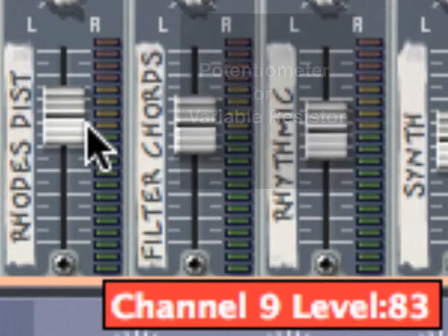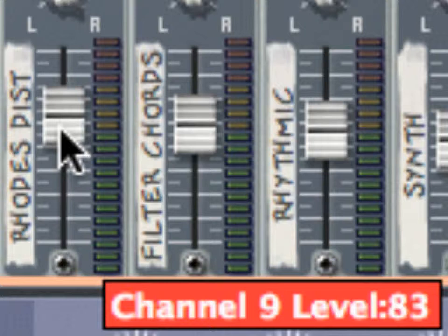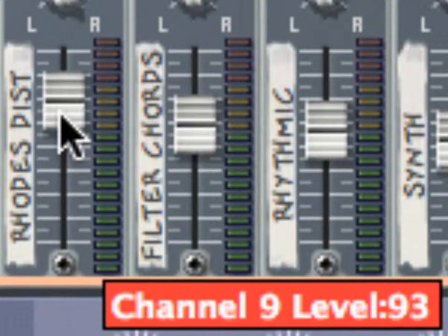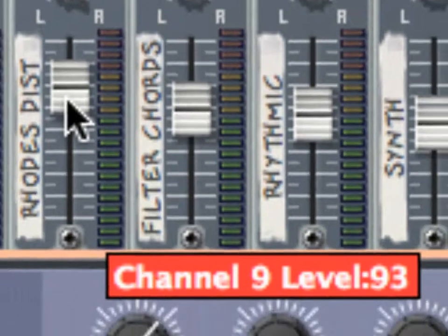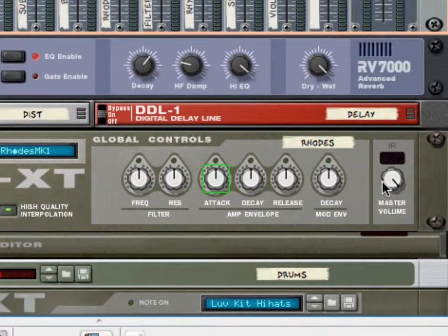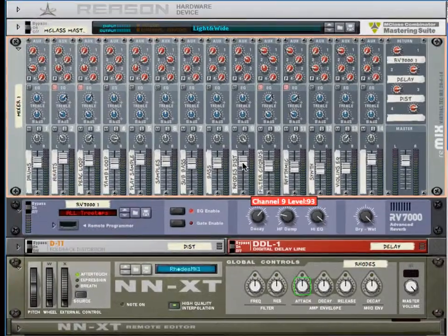This is a simple control which varies the amount of resistance and therefore the signal level. As a rule, it is desired that the fader be around 0 dB for optimal sound quality, although this will obviously vary a lot. Remember, there are two ways to adjust a channel's volume: the input gain, which is found on each device, sending it to the mixer, and then the fader.